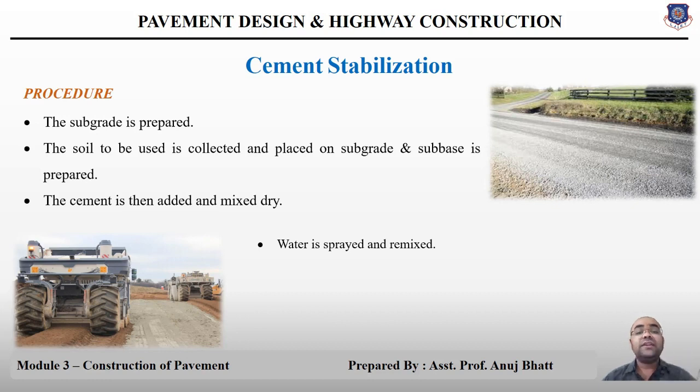The moisture content of the mix will be slightly drier than the OMC for sandy soil and slightly wetter for soil containing too much clay. That OMC is nothing but the optimum moisture content.